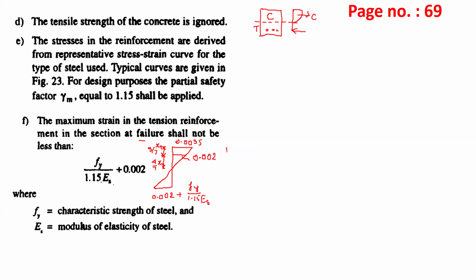And then if we draw this stress diagram, you may be asked to draw the stress and strain diagram. We have the neutral axis over here, and then this will be TU and here we have CU. CU is always in the rectangular portion, because if you calculate this value, we have 0.416 XU. So that is in the rectangular block.